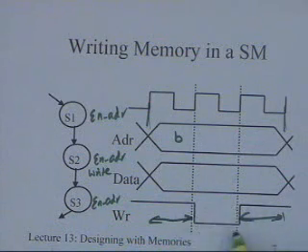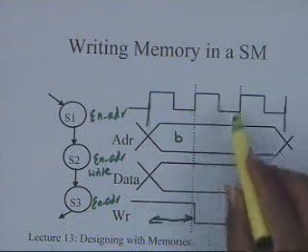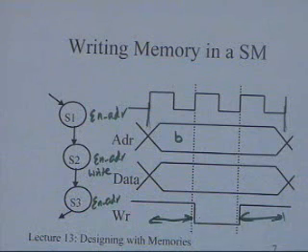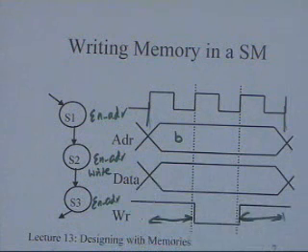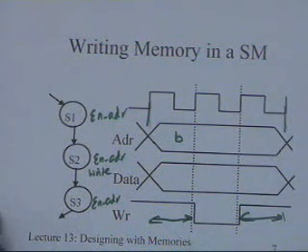Whatever is your write pulse width, the minimum pulse width should be there for your state machine cycle. So this is a safe design and will anyway work without much effort because you have ensured that all your timings, all your restrictions are followed very well.